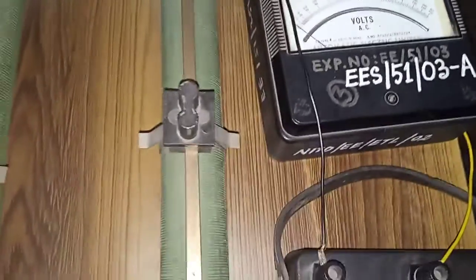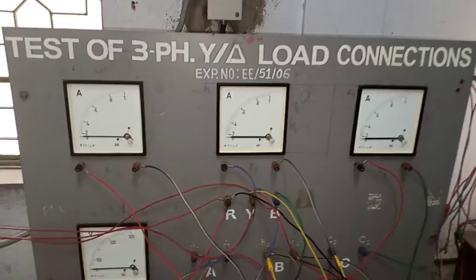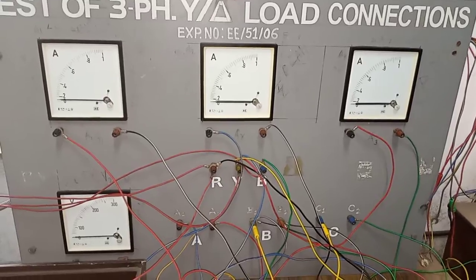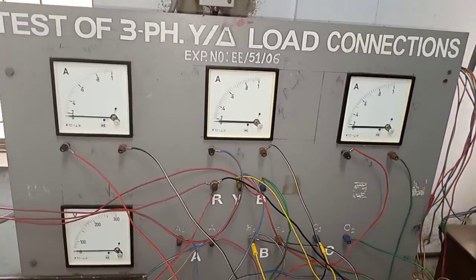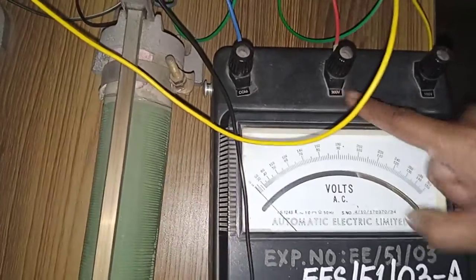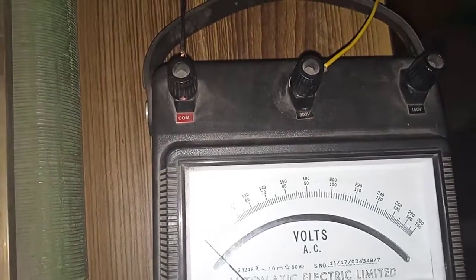Since we are dealing with three-phase supply, in India, normally at LT level, the three-phase line-to-line voltage is normally 400 volt and above. Phase voltage is around 220 volt and above. So since 220 is greater than 150, even if it is a phase voltage, we prefer for safety to connect it at the 300 volt terminal during our experiment.